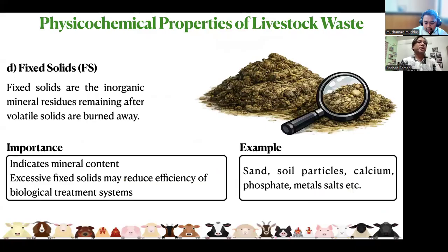Now the fixed solids. Fixed solids are inorganic material residues remaining after volatile solids are burnt away. So if we remove the volatile solids from the total solids, the remaining inorganic part is known as the fixed solids. Now the importance of fixed solids. It indicates mineral content. It means fixed solids show how much inorganic materials and inorganic mineral salts are present in the waste.